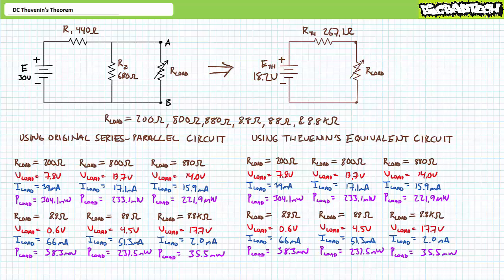Lastly, I need to remind you that Thevenin's theorem is an essential rite of passage in your development as an electrical engineering technician and will become a necessary and frequently employed tool. Later theorems like the maximum power transfer theorem, and to a lesser degree Norton's theorem, are predicated upon your understanding of Thevenin's theorem. In conclusion, we learned to employ Thevenin's theorem in an effort to simplify a complicated series parallel linear two-terminal network. Ideally, the original and Thevenin's equivalent circuit will behave identically to each other. However, the Thevenin's equivalent circuit will be notably easier to build and to solve for desired electrical quantities.